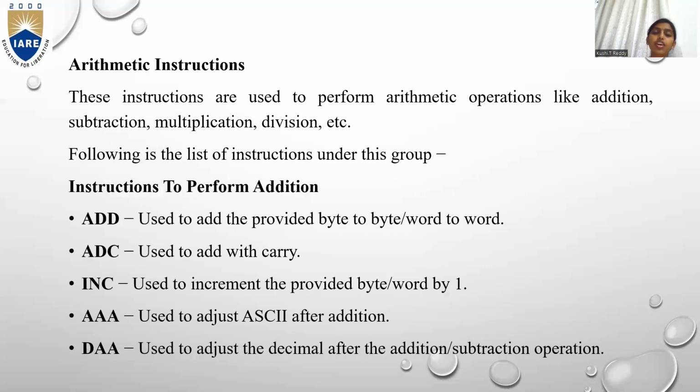So let us now learn about the arithmetic instruction set. These instruction sets are used to perform arithmetic operations like additions, subtractions, multiplications, divisions, etc. Instructions to perform additions. ADD is used to add the provided byte to byte or word to word data. ADC is used to add with carry. INC is used to increment the provided data or a byte by 1. AAA is used to adjust ASCII after addition. DAA is used to adjust the decimals after the addition operation.